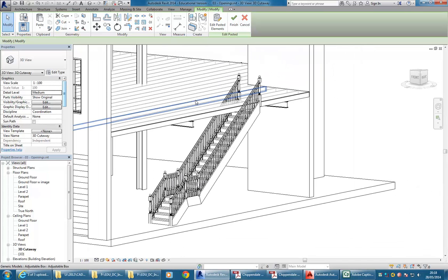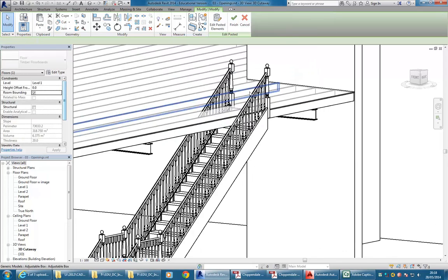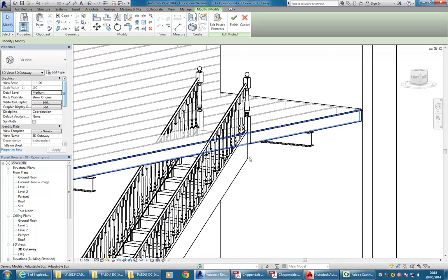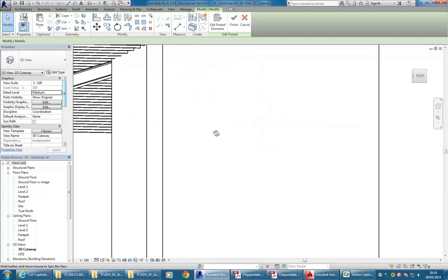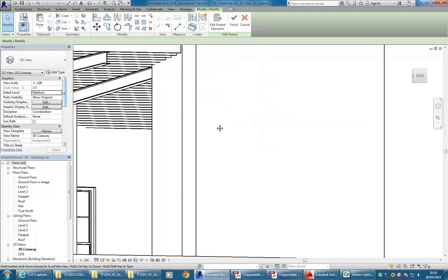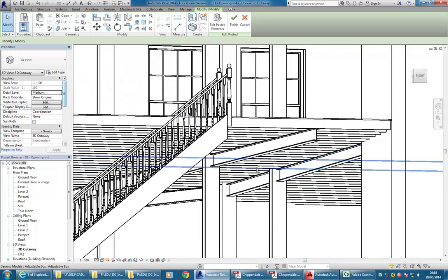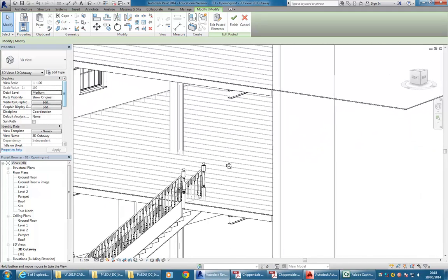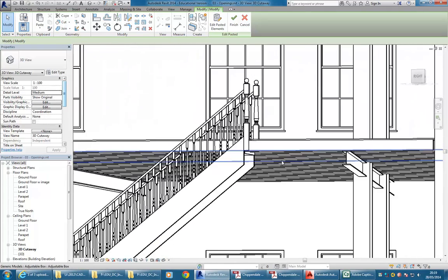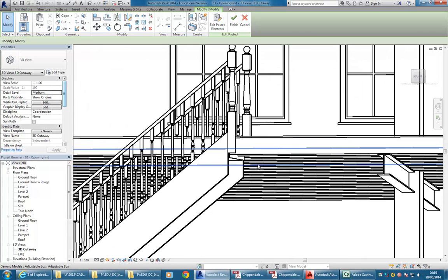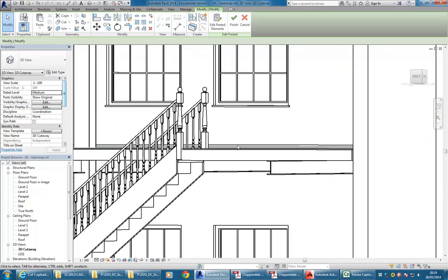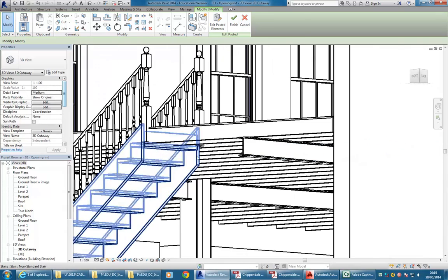And so then we've got the floor above, where we need to think about, again, what's happening with the structure there. If you want to get really carried away with it, you can put in the blocking pieces that they'd have behind that stair, to support those joists, with some sort of timber piece that comes along the front there. They'd have to do all sorts of things, but as long as it looks believable, you just want to make sure that the joists there at least go up to that stair.